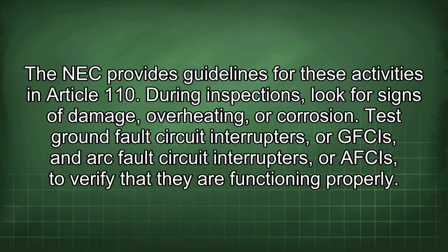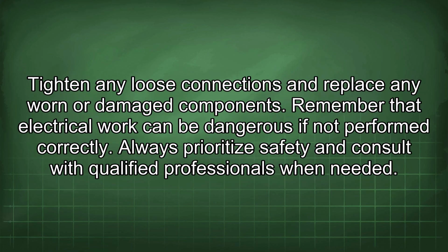During inspections, look for signs of damage, overheating, or corrosion. Test ground fault circuit interrupters, or GFCIs, and arc fault circuit interrupters, or AFCIs, to verify that they are functioning properly. Tighten any loose connections and replace any worn or damaged components.